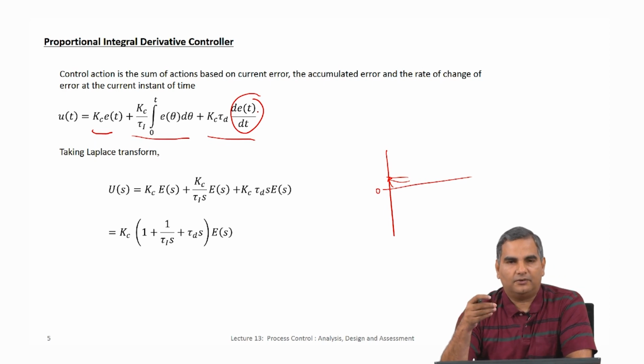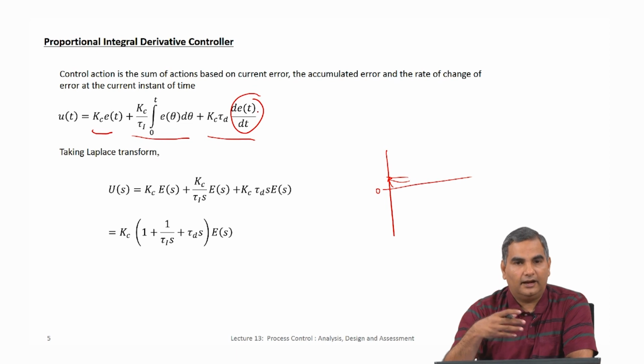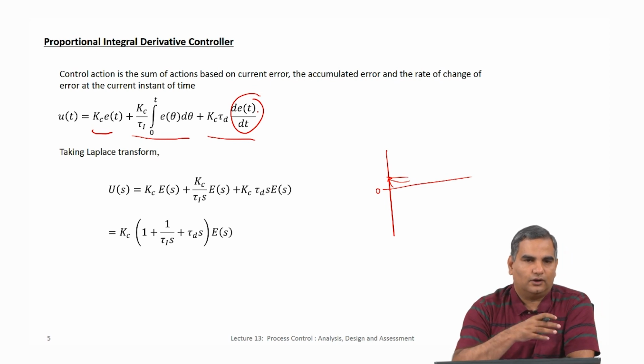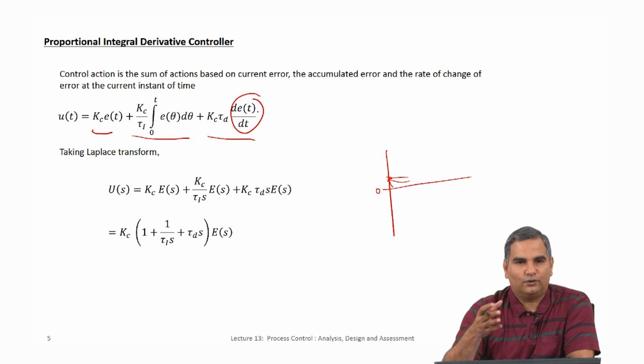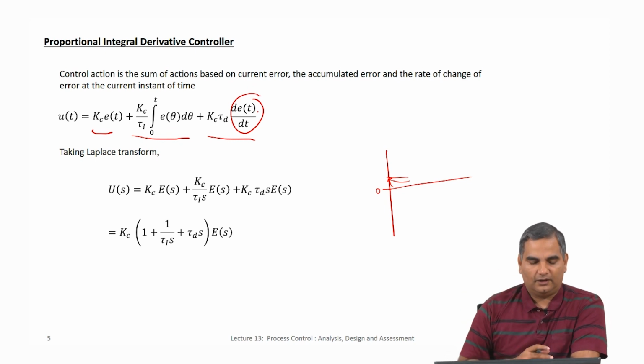The third type of controller looks at the current error, all the errors that were seen, and what is the rate, so in the future how the error is likely to change. So, this takes into account current, past and future. Proportional integral takes into account only current and past, and proportional controller just takes into account current, right. So, that is how you want to think about this.